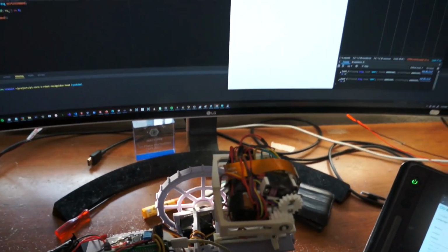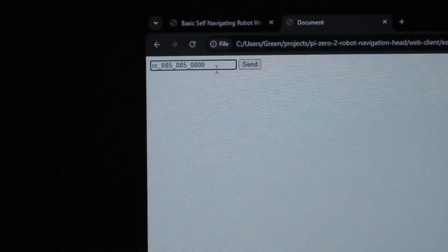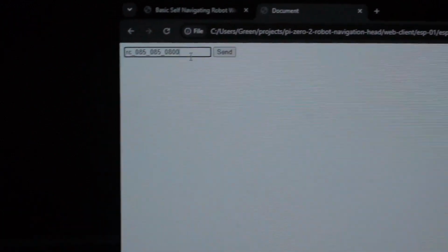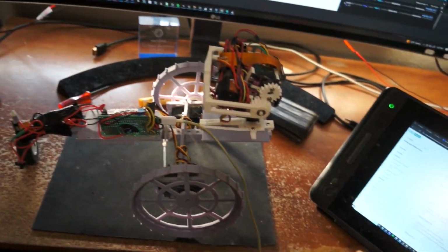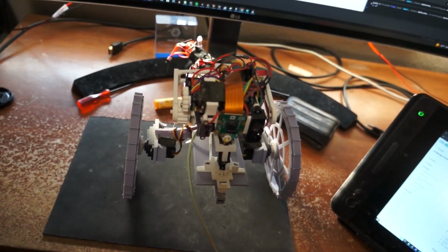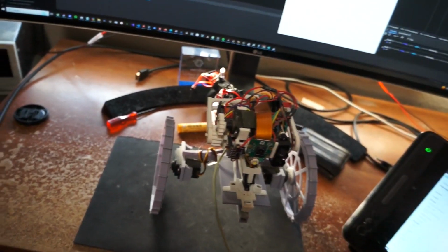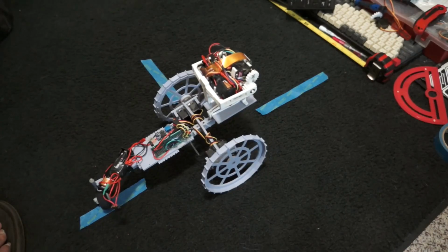Alright, so production value is really dropping here, but you can see this is the new command, right? Raw command, 85 degrees, 85 degrees, 800 milliseconds. And then if you watch, it's plugged in. I click that button and it'll turn, yeah. So this way I'll be able to just dial this in without reprogramming the Arduino every time. That's pretty good. Call it like 890.